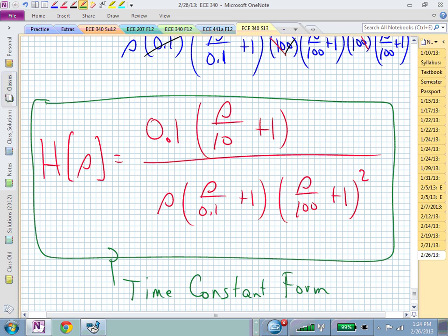And we also need to figure out how to plot the Bode plots for poles or zeros at the origin. Those are all we have to do. What I'm really going to do is collapse these quadratics into terms that look like two linear factors at the same location. So all you have to learn for this class is how to sketch constants, linear factors, and poles and zeros at the origin, and put them all together.